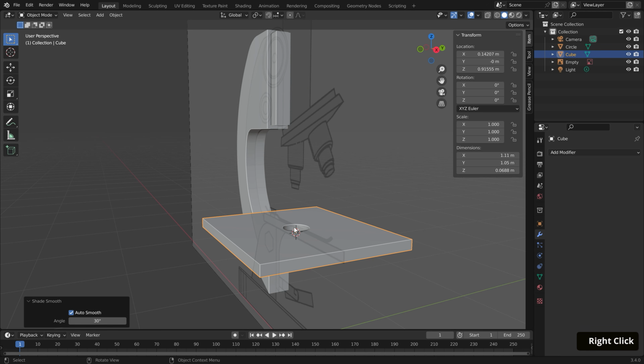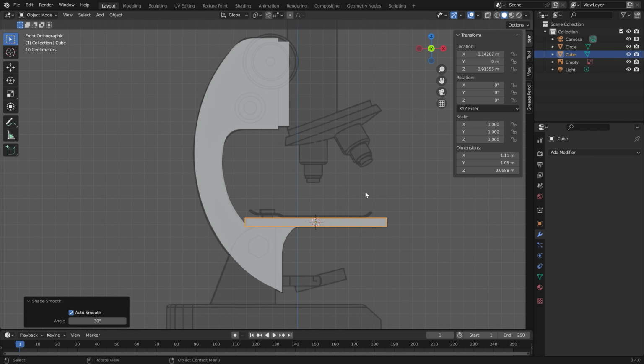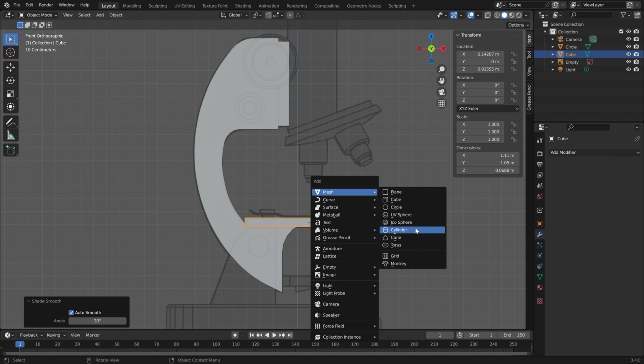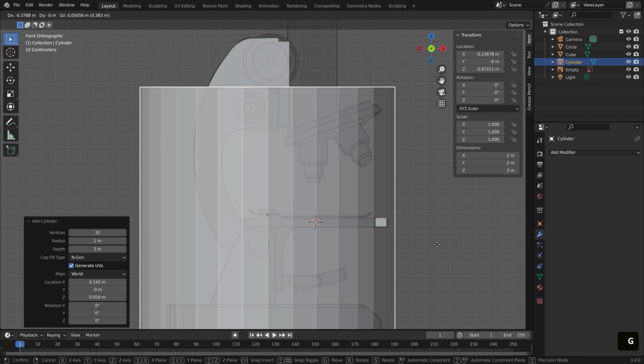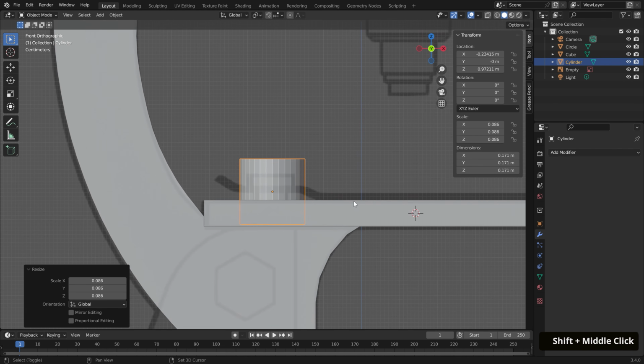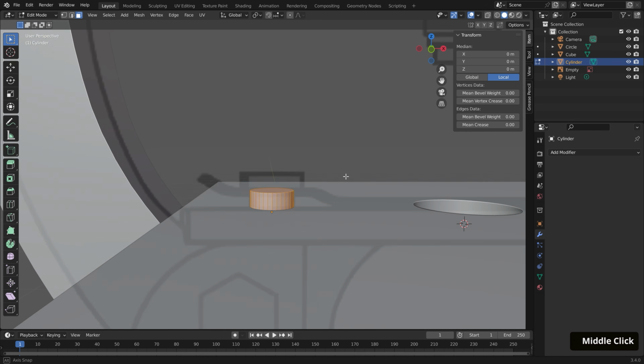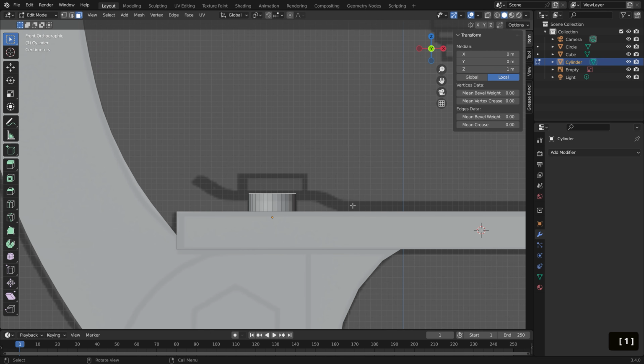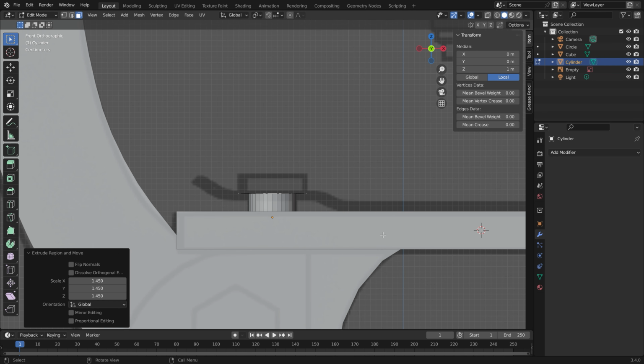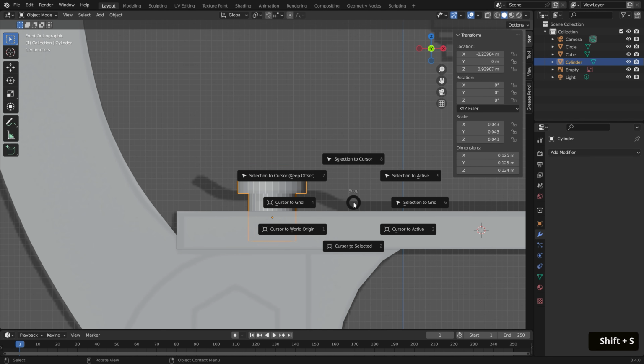Now, we'll create the clips that sit on top of the stage, and we'll start with the fastener. So in Front View, hit Shift A and bring in another mesh cylinder. Move it to the left over the reference and size it down until it fits the radius of the bottom portion. Tab into Edit mode, and with Face Select, select the top face of the mesh. Go into Front View and hit E then S to extrude and scale it outward. Then hit E again to extrude upward to form the head of the fastener, and until it matches the height of the reference.